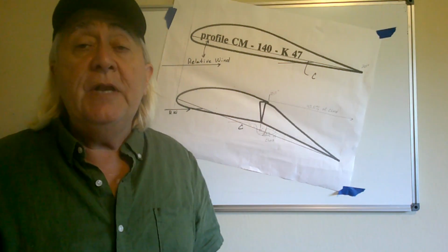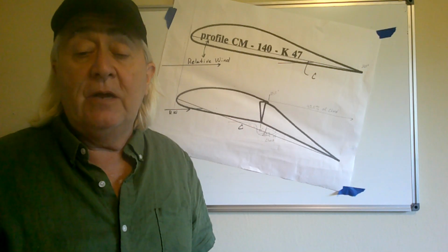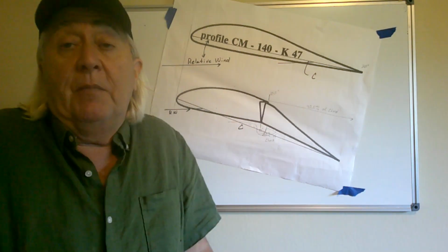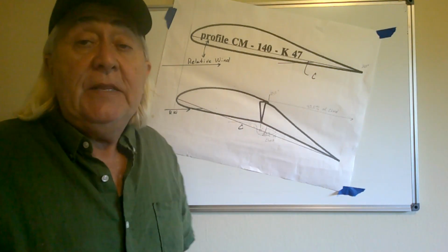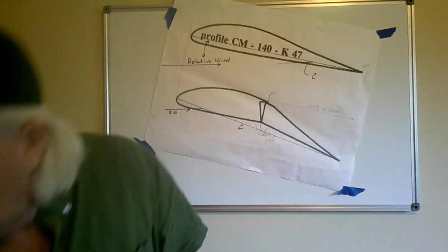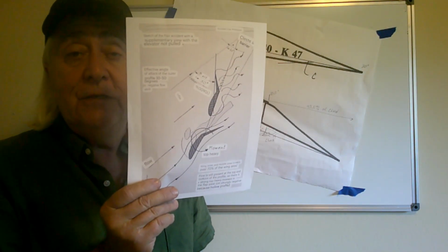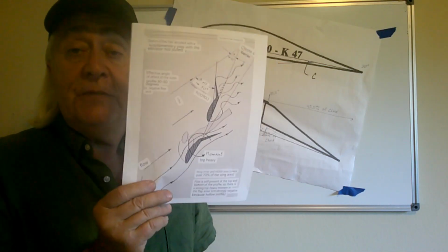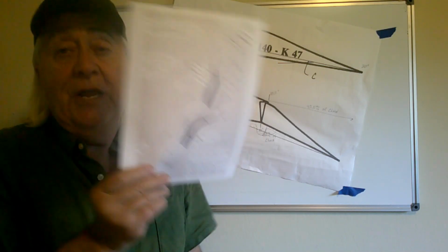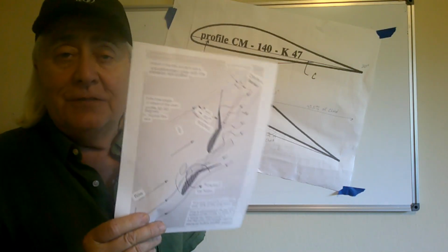I know people will never let go of their thoughts about it was separated flow on the elevon. It might have contributed to this. This does explain how you end up like this. How do you get into this configuration? You stall. Does that make this the root cause of the crash? No. The stall is the root cause of the crash.